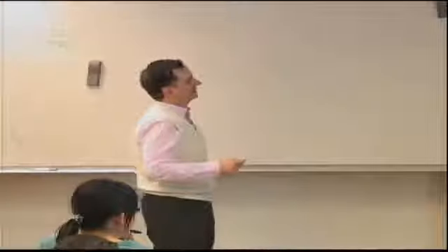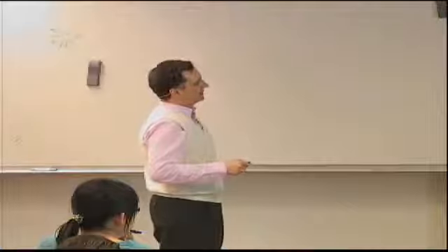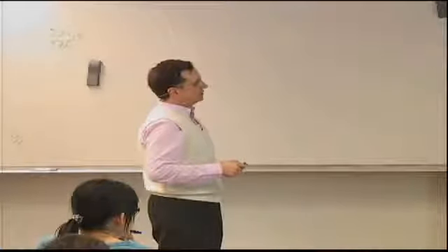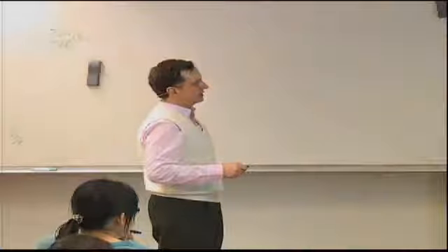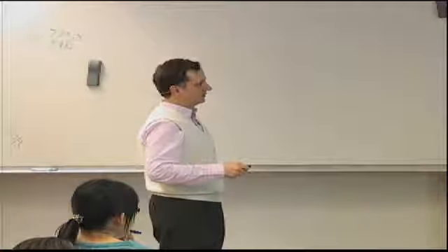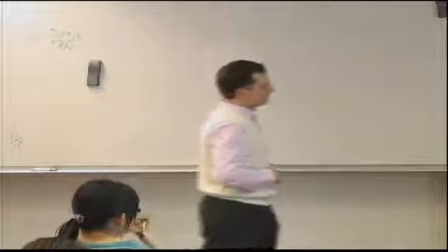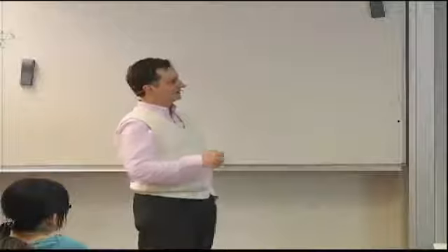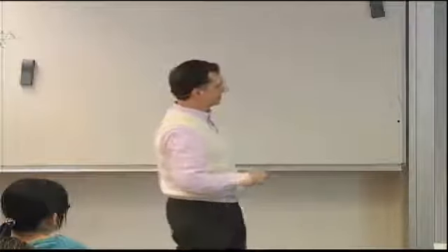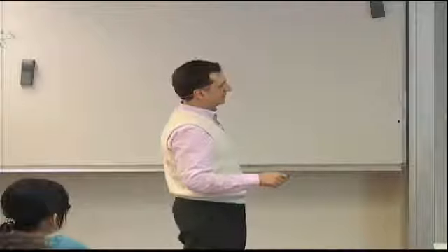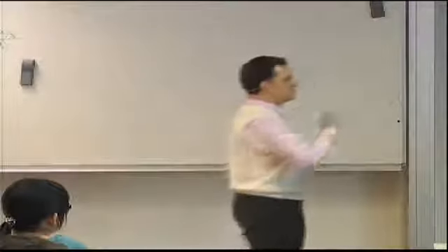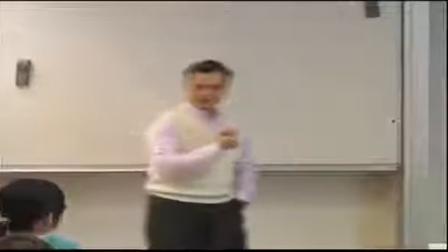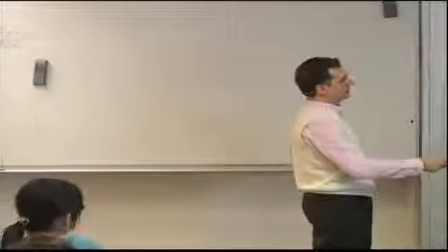Now, if I know my neutral axis, then I know that under a bending moment I will have a compression part and a tension part, and I need to calculate my maximum compressive stress, which is given by the bending moment times the distance from the neutral axis divided by I. If I know the bending stress, I can calculate the corresponding strain. This being a beam, I can directly divide by the Young's modulus, which is this one. So this gives me my strain. So this is my applied strain for a given bending moment and a given selection of B2, which means that as I change B2, this would change.